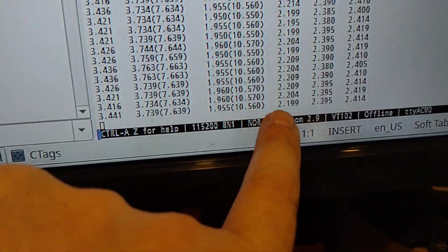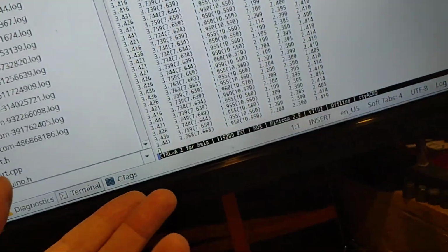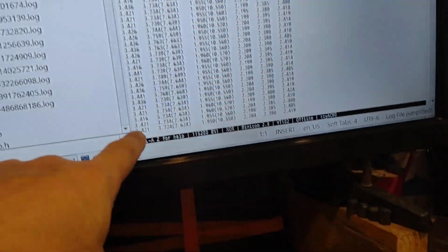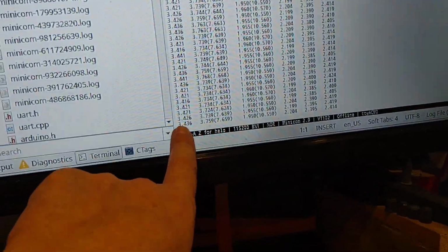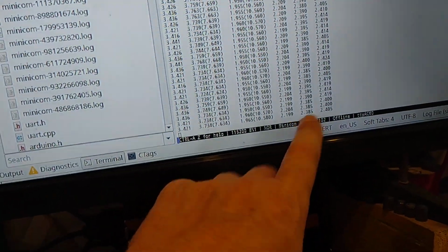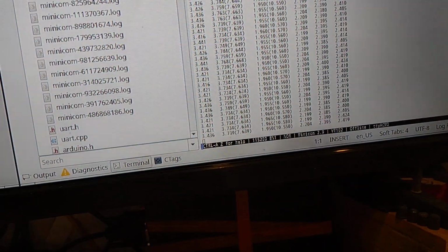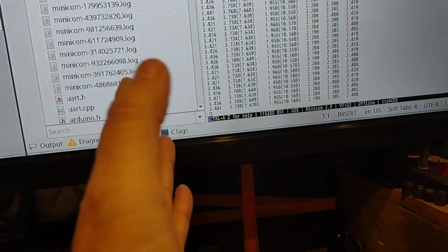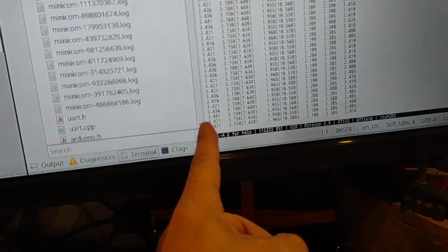So you know what the pack voltage is, and you just divide it by 3, and that gives you the voltage that you're supposed to be aiming for, at which point you cut off the charge. So that's how it works. You focus on that one and keep going until it hits the average pack voltage. And then, okay, we're done. Switch that one off. We're charged. We balance that cell.